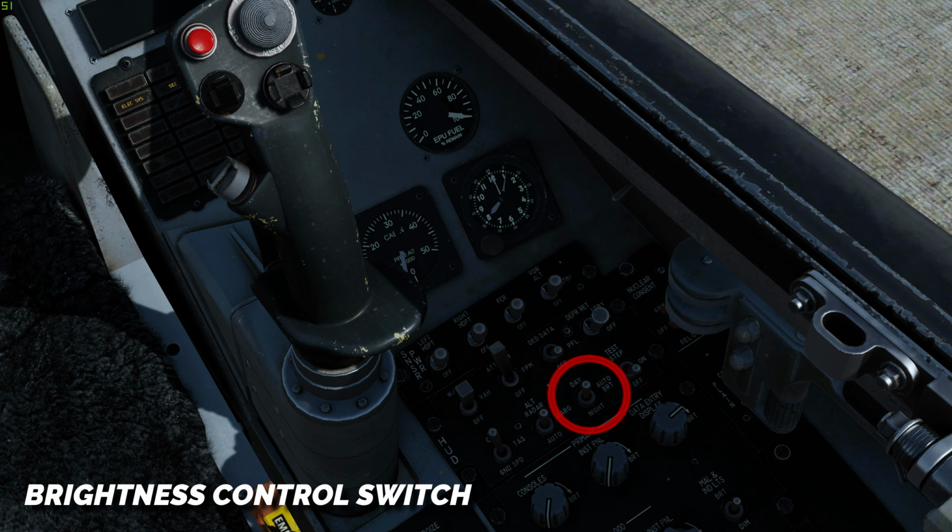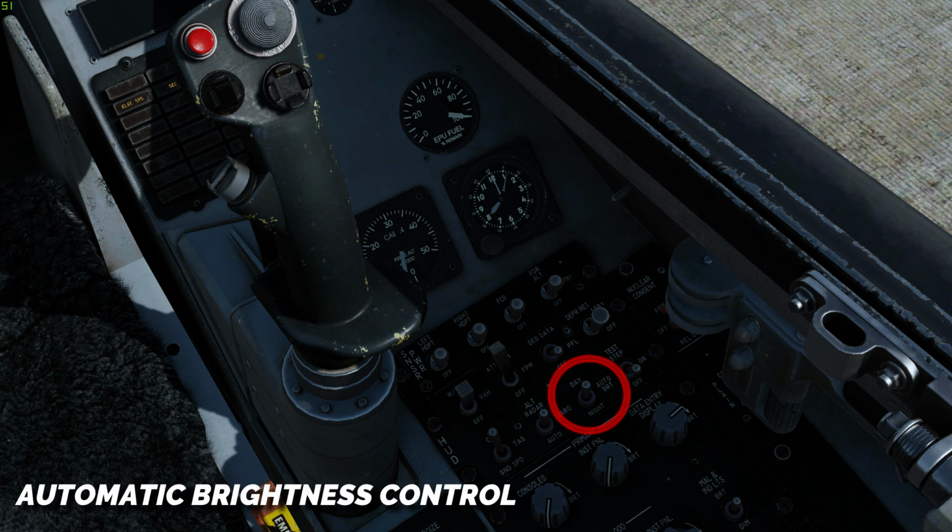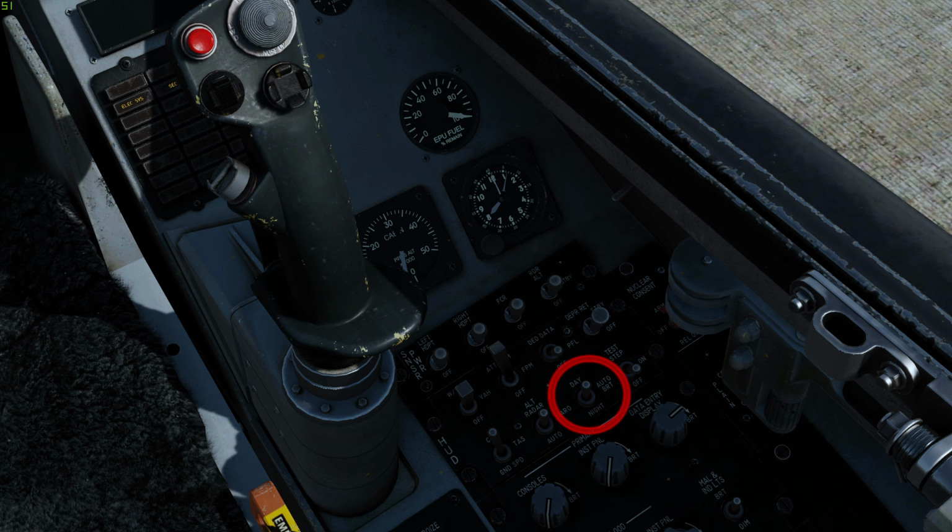In the day position, brightness will be set to a range from no visual perception to full intensity. In the night position, brightness ranges from no visual perception to 1/20th of full intensity. In the automatic position, an ABC sensor is used to maintain a pilot-selected potentiometer setting.